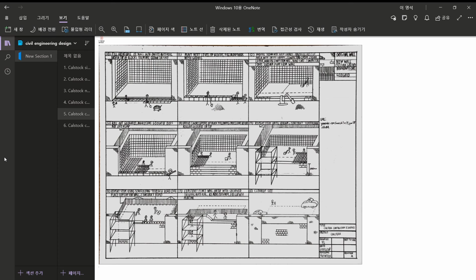To ensure that the workers are able to reach the half-constructed wall safely, we will be constructing scaffolding when the wall reaches 1 meter. When the wall reaches road level, we will place top caps for the wall and construct the road, after which the fence wall on top will be constructed using salvaged material and the pathway will be removed.